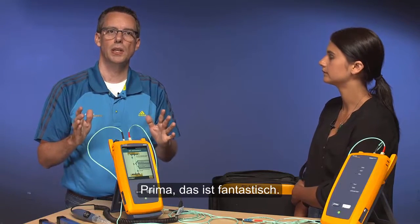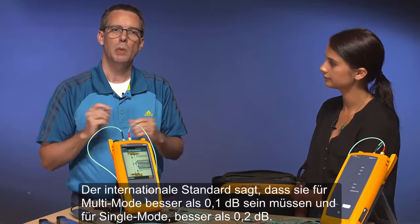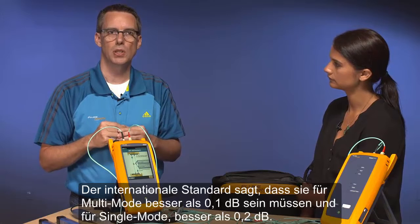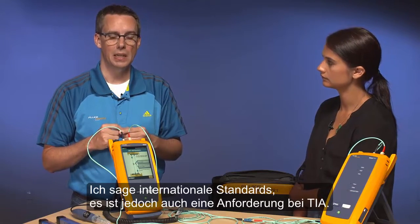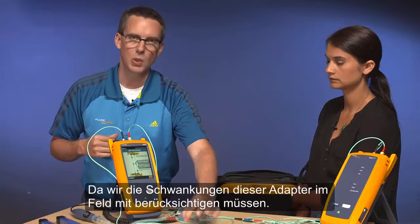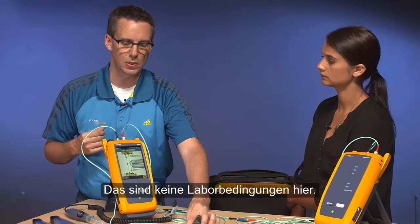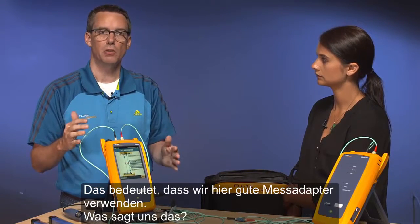Nice, that's fantastic. The international standards say for multi-mode that it needs to be better than 0.1 dB, and for single mode better than 0.2. I say international standards, that's also a requirement in ANSI TIA now as well. The tester here actually sets a soft limit of 0.15 dB because we need to take into account the variability of these adapters in the field. This is not quite laboratory conditions here. So it passed. That means we got good test reference cords.